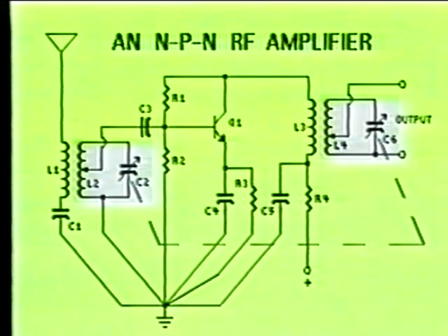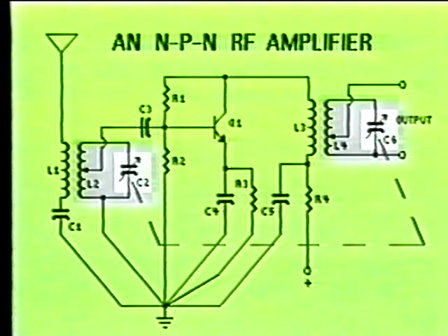The circuit also contains two resonant tank circuits. The input tank circuit consists of inductor L2 and capacitor C2. The output resonant tank circuit consists of inductor L4 and capacitor C6. As you should have noticed, capacitors C2 and C6 are both variable capacitors, and they are gang-tuned. The purpose of gang tuning is to allow more than one stage to adjust at a time. By adjusting both the input and the output tuned circuits simultaneously, you can increase the selectivity of the RF stage.